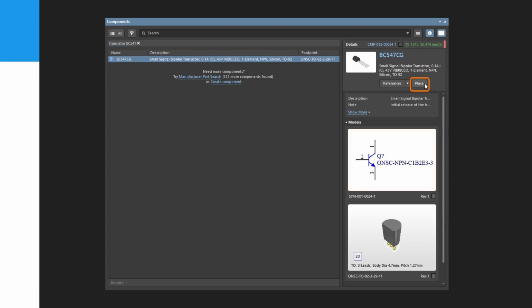For a simple design such as this, 100 mil is a good choice. Then, next step, once you're happy with the transistor's location, click the left mouse button or press Enter on the keyboard to place the transistors onto the schematic. The location can be changed later if required.